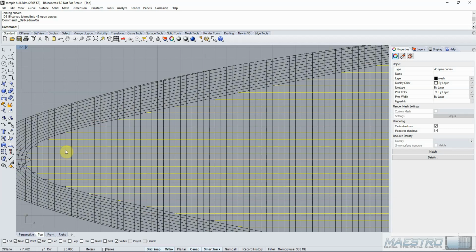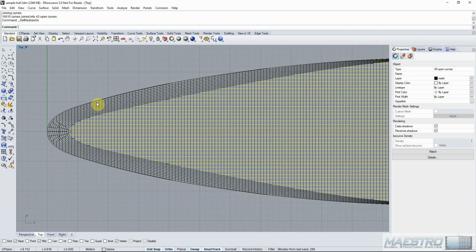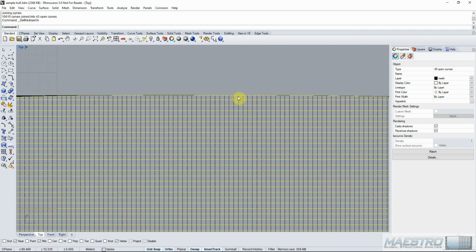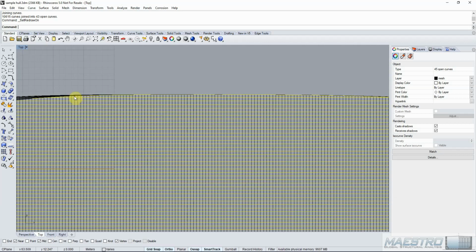Now, typically in the bow, this may transition to a transversely framed, and a lot of these stiffeners will likely end at the nearest frame and have intercostals put in up forward of them, as well as on the side shell here, or near the side shell rather, there may not be enough room to weld, so they'll stop the stiffener a little early and put in intercostals.